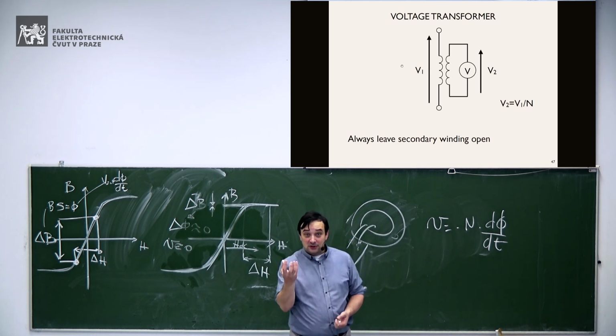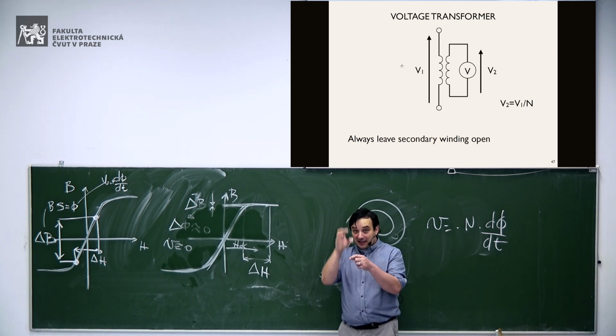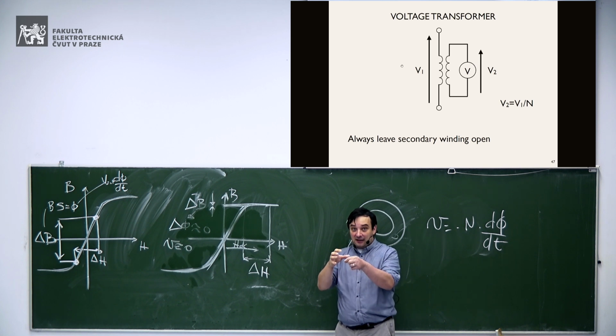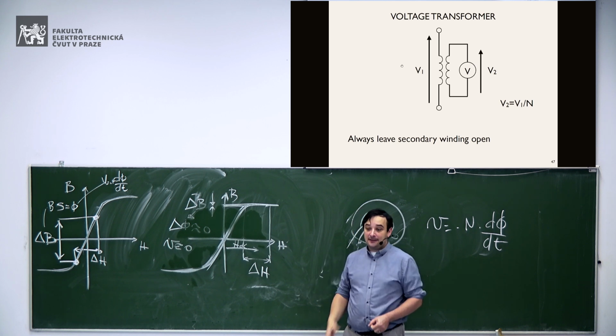for instance, put the current transformer in a place far away from the case of the instrument. So you are far from any point you could put the magnet, and the further you are, the lower is the magnetic field you can create. Okay?